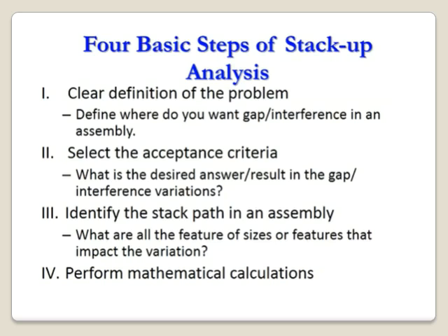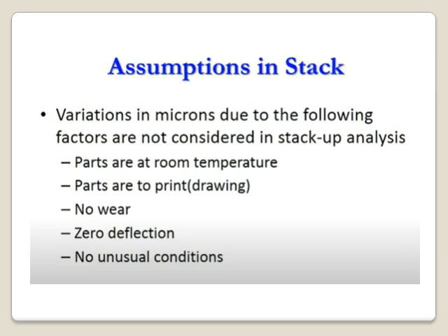Fourth, perform mathematical calculation. Here we'll make some assumptions in the stack. Variations in microns due to the following factors are not considered in stack-up analysis: parts are at room temperature, parts conform to print and drawing, no wear, no deflection, no unusual conditions.